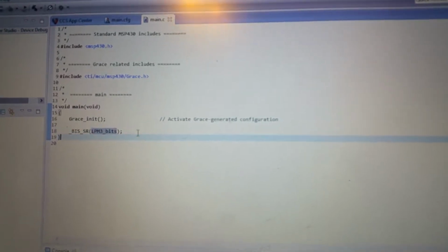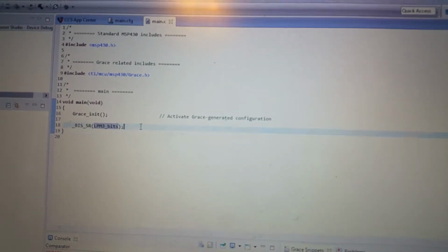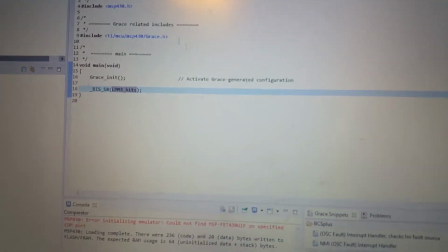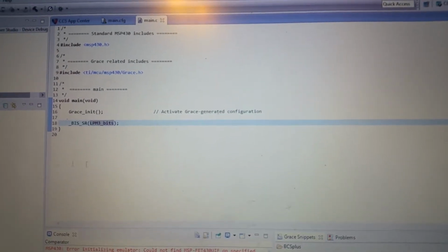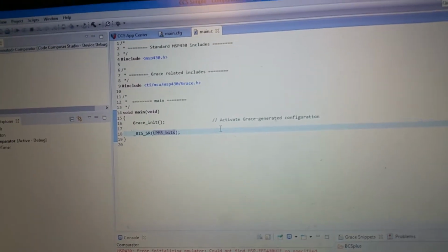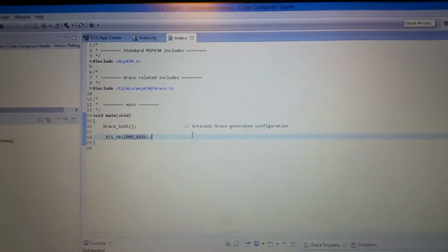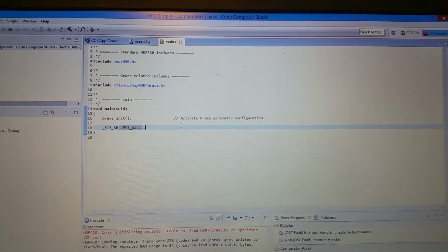That being said, I set it to low power mode 3 and just let that run. This low power mode 3, I believe, according to descriptions, the active current is about 1 microamp. I'm not sure, but basically it disables features of the MSP430 that we don't really need for this project.